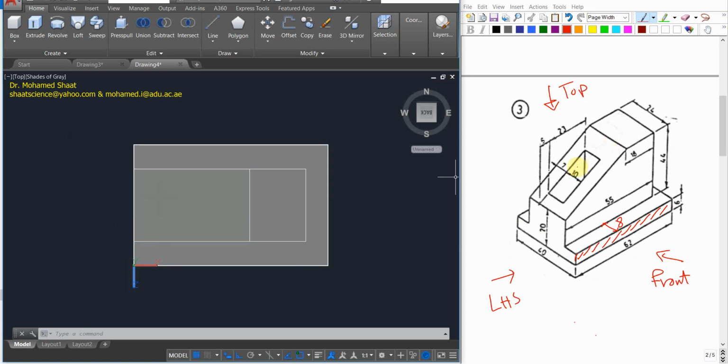Okay, so what are the dimensions of this rectangular shape? It is gonna work in this way. Instead of drawing over the inclined surface, I'm just gonna draw over this horizontal face. You can even draw over this top face, right? With 23 length, and the width is 10 millimeter. Because this edge is 10 millimeter, and I'm extending this direction with the 23.